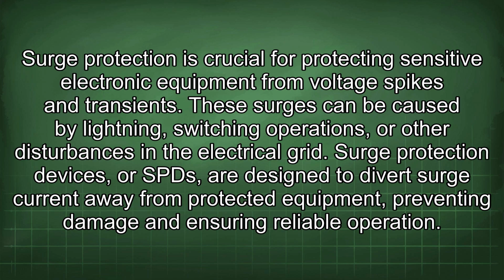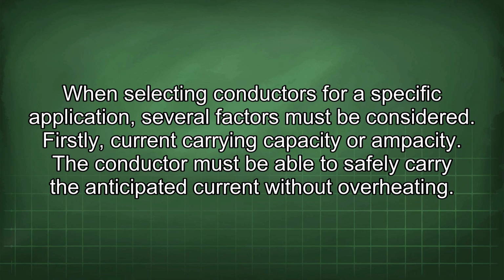Surge protection devices, or SPDs, are designed to divert surge current away from protected equipment, preventing damage and ensuring reliable operation. When selecting conductors for a specific application, several factors must be considered. Firstly, current carrying capacity or ampacity. The conductor must be able to safely carry the anticipated current without overheating.